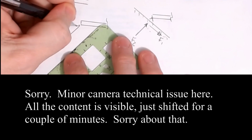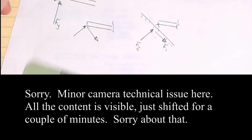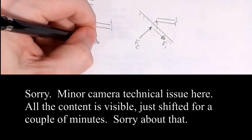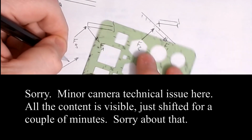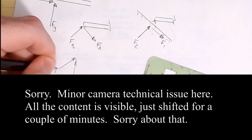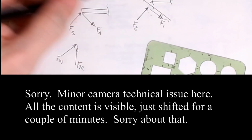Okay, I could also draw this one, and if for whatever reason maybe all my forces are at some angle, I could draw it this way. Okay, but I can write them as pairs. So here's an FA, here's an FB. In fact, they don't even have to be 90 degrees to each other. I could do this, let's call this, for lack of a better word, FM and FN. So long as the resultant of this, because remember, I can take two forces and I can always turn it into an F force using our parallelogram law or using our components rules for vectors. Okay, as long as this F is the same for all of these pairs, the free body diagram will work.